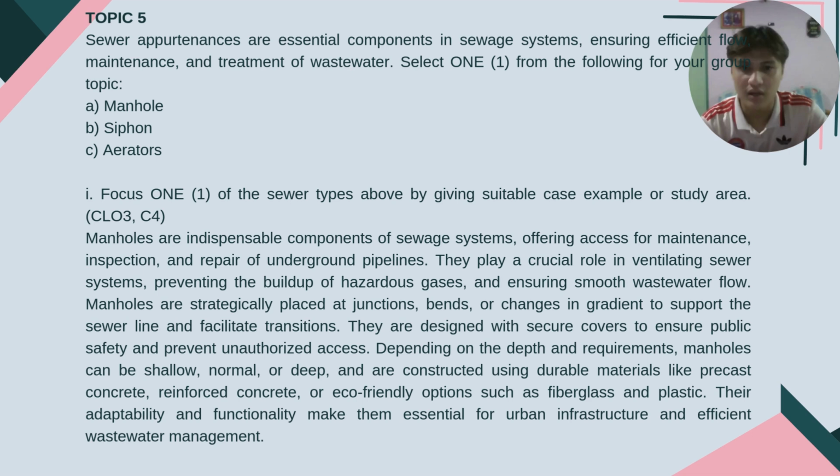Manholes are essential components of sewer systems, offering access for maintenance, inspection, and repair of underground pipelines. They play a crucial role in ventilating the sewer system, preventing the buildup of hazardous gases and ensuring smooth wastewater flow. Manholes are strategically placed at junctions, bends, or changes in gradient to support the sewer line and facilitate transition.